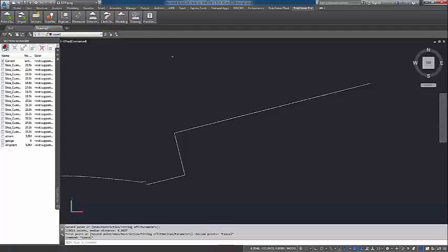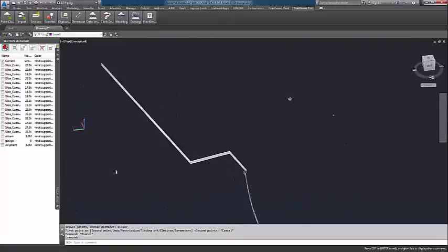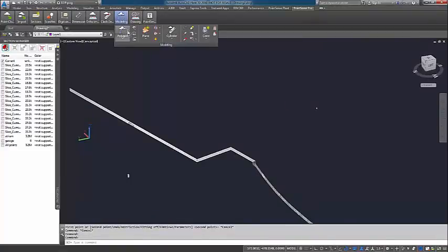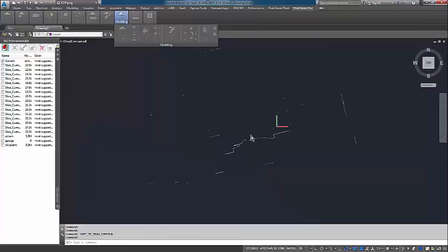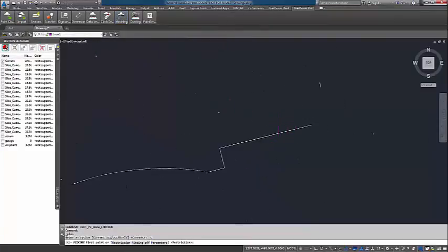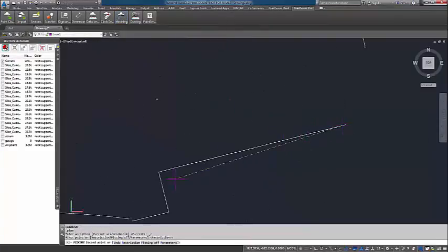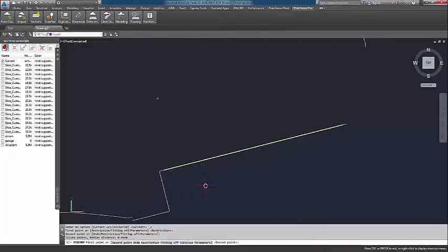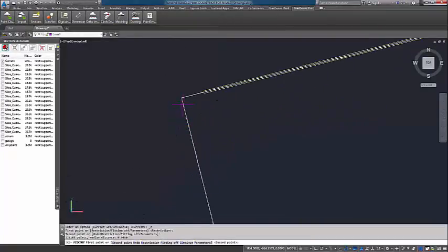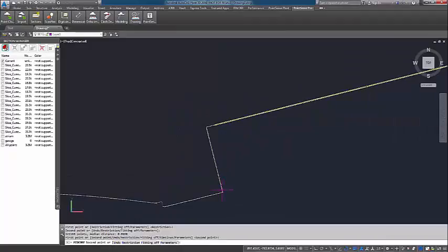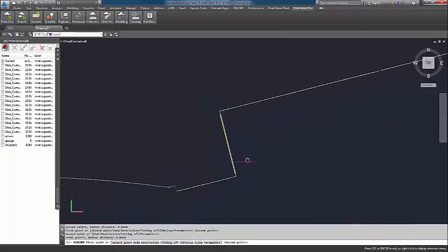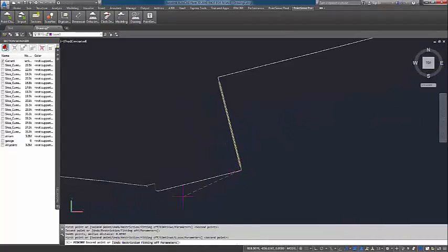Section 6, line fitting. After creating a slice using our sections tools, we can digitize it by using a line fitting tool like Fit Outline Plan. Fit Outline Plan is meant for straight geometry, like the walls we see on the right here, and we just pick 2 points close to the ends of the wall, 2 points on our next wall, and the software fits to those points inside of the yellow region, creating a best fit line.